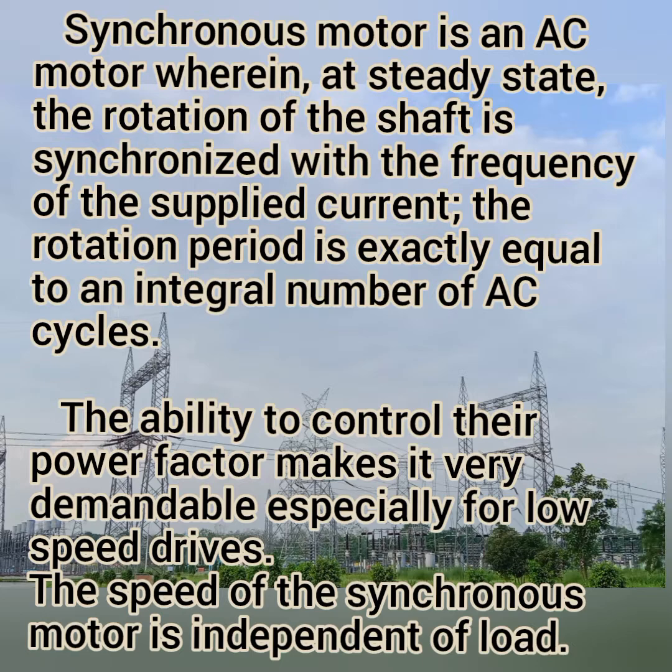Coming to the topic, a synchronous motor is an AC motor in which, at a steady state, the rotation of the shaft is synchronized with the frequency of the supplied current. So the rotation period is exactly equal to an integral multiple of the AC cycles. The main thing is that it can be used for power factor control for low speed devices. Also, the speed of the synchronous motor does not depend on your load, which means it is independent of varying load, and mainly it can be controlled by the frequency of your AC source.